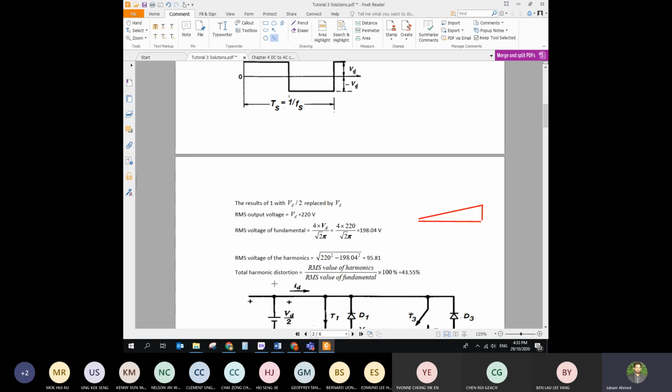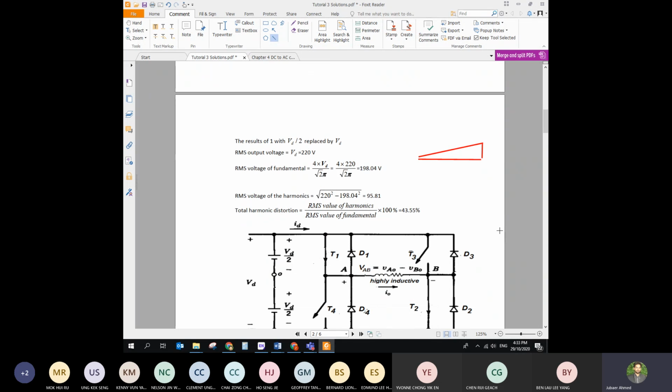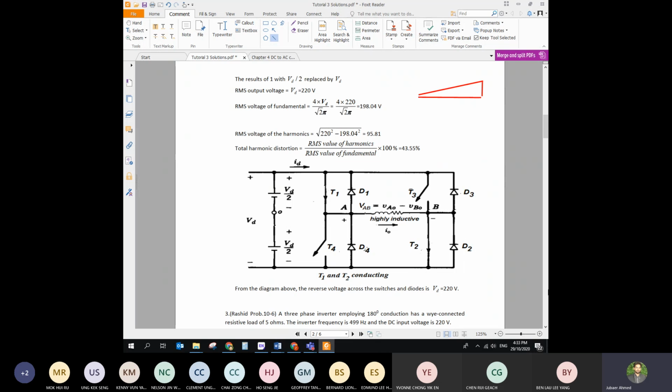So that's why from the solar field, we have to convert it from DC to AC. Then we have to supply to our household, or we have to connect it to the main grid. So that is the place the inverter will come into function. And since you see that the inverter's output is not pure sinusoidal, it has many harmonics, that's why we have to design another special circuit here to filter out the harmonics.